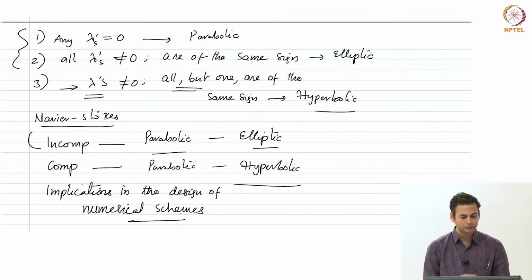You usually will have a lot of difficulties in converging the solver. So, there could be some special treatments which you have to borrow from the concepts of incompressible flow solutions to be put into the compressible thing, okay. In which case you can actually probably just be well off solving the incompressible flow equations rather than the compressible ones, because the speeds are so small that there are no density variations. The density variation is less than 5% or 3%.